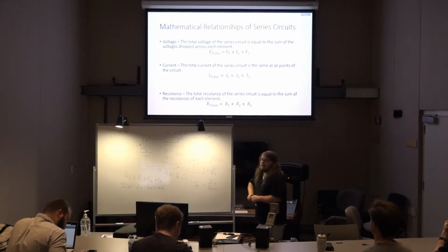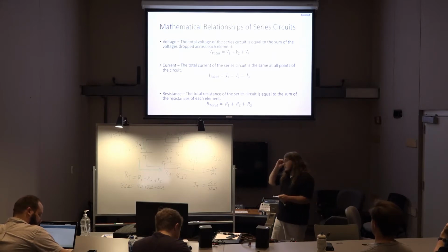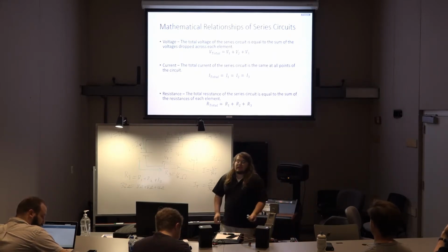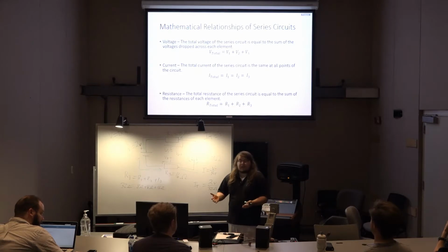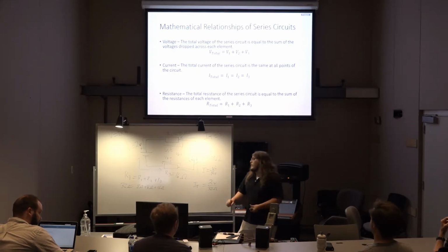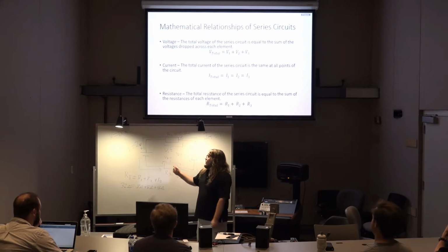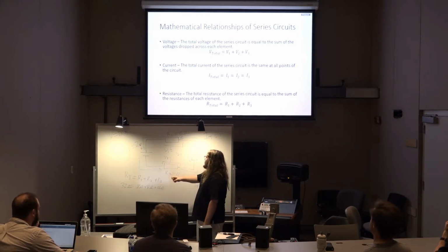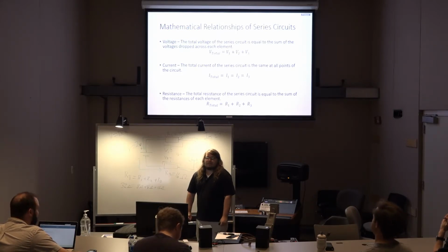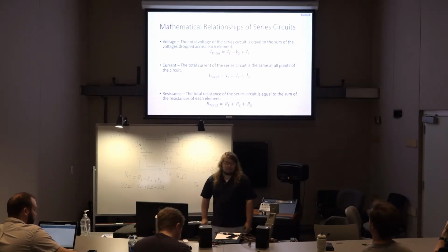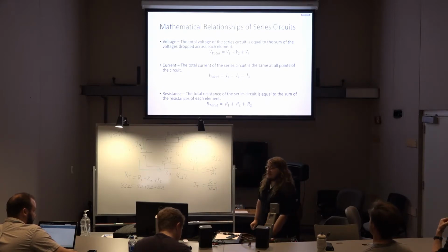So, we have found out a couple of pieces of information that will help us here. In that last Socrative question, we figured out the current through the circuit, which was 62.5 milliamps, correct? And it stayed constant throughout. So if we have 62.5 milliamps of current through this lumped element resistor 3, how do we find the voltage? Would it be 62.5 milliamps times 16? Yes, that is indeed how you would figure it out.